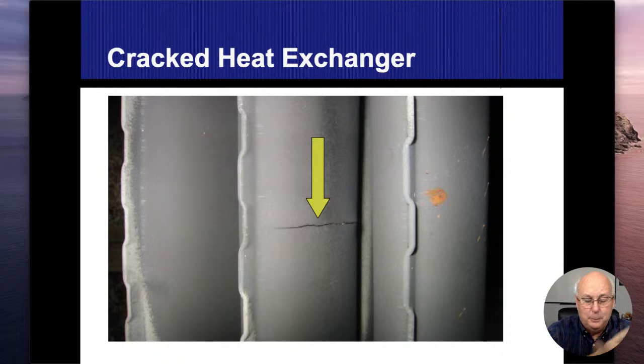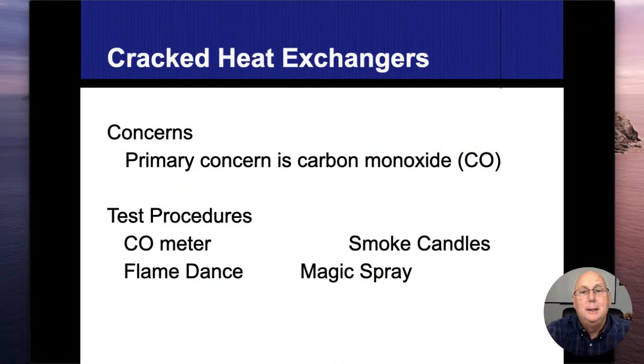Same thing with, let me back up a slide here. Smoke candles, this is something I really don't recommend that you do. But you can actually put a lot of smoke inside the heat exchanger. And if there is an opening in there, that smoke will pass through the heat exchanger as long as the blower fan's not running. And then that smoke might be coming into the house. But this is somebody else's home, and I'm not a big fan of putting that in there.